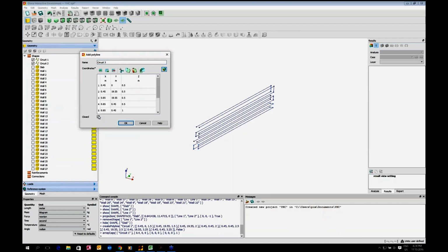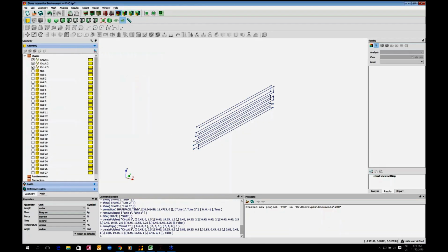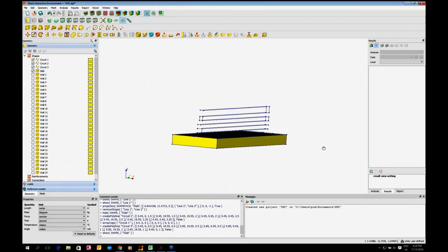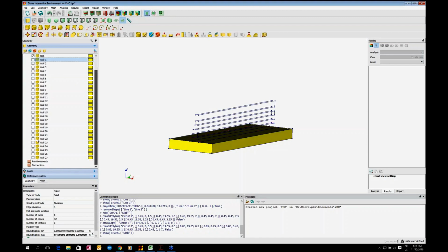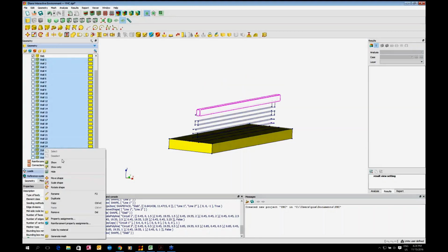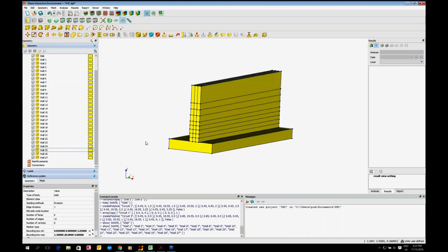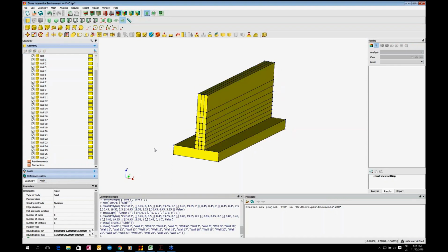Make sure that this is off and click OK. So I have my model, I have position of the slab and the rest of the segment that's gonna be active on the model. So what I'm gonna do now, I'm gonna define a boundary condition as a kind of environmental or external temperature to the model.